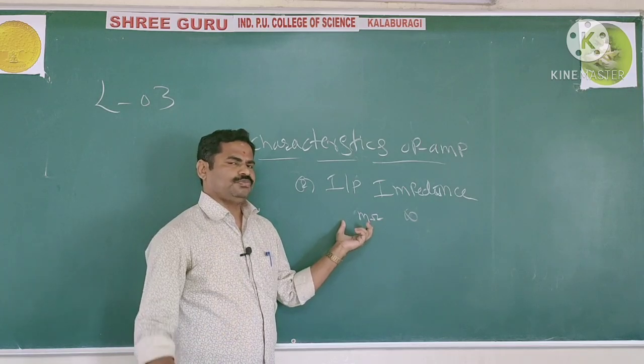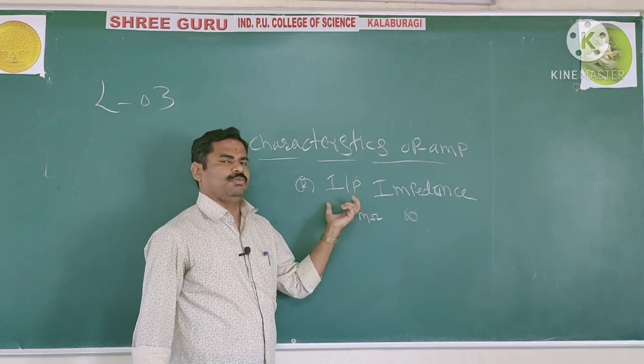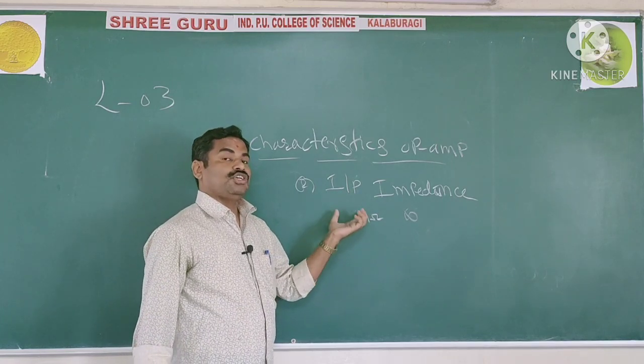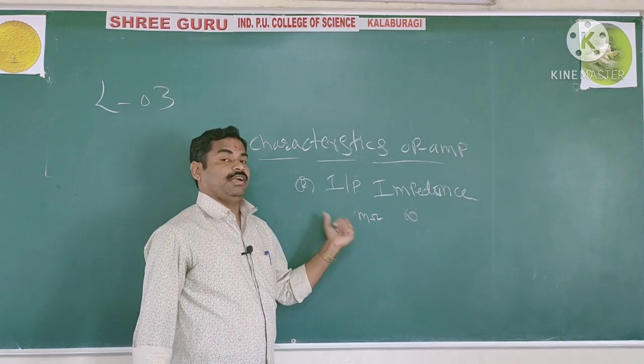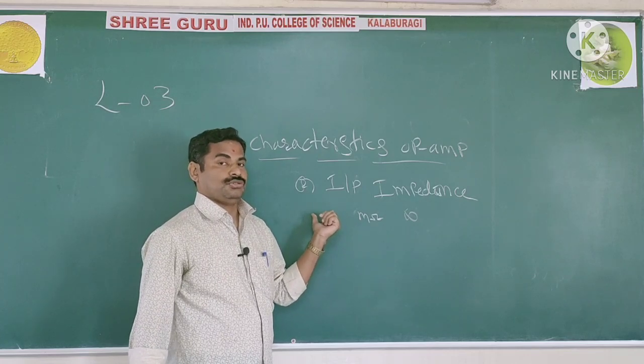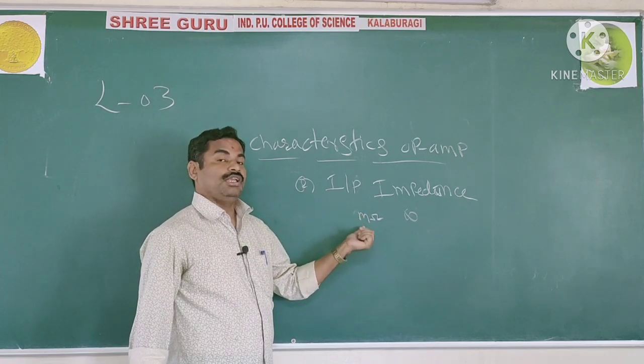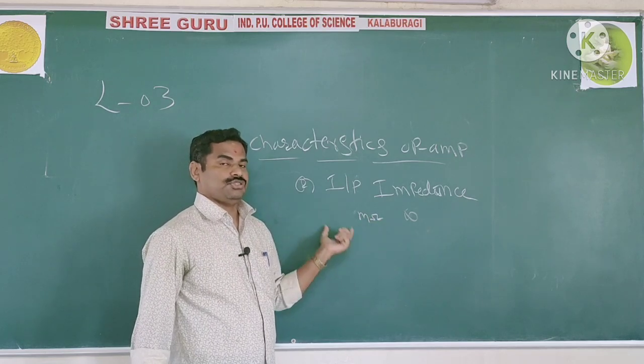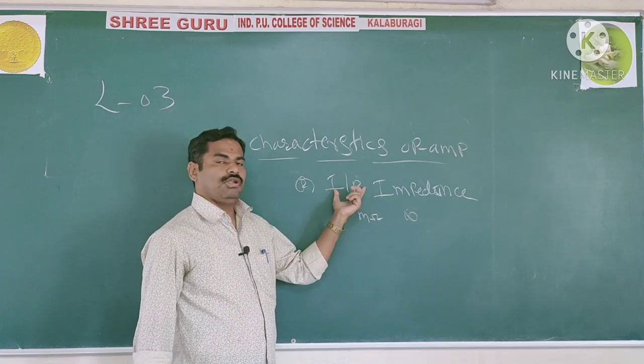And as we know, we always require high input impedance. Why do we require high input impedance? Because it does not affect your voltage and current source. It is not affected by the loading effect of the previous stages. That's why we want high input impedance.